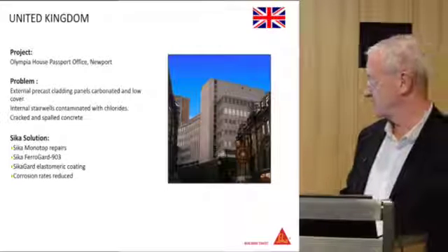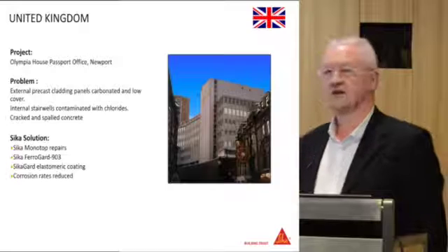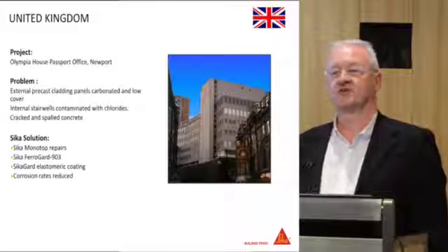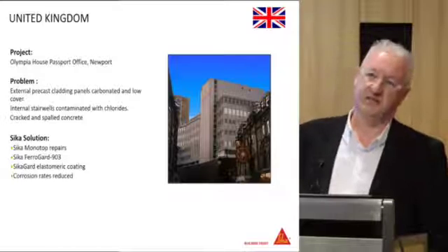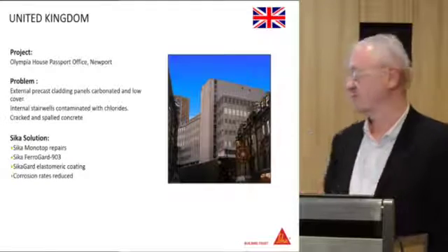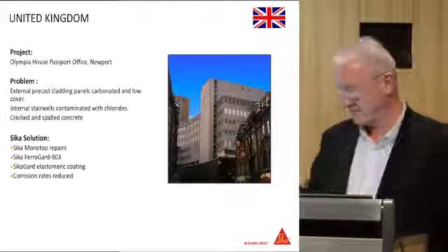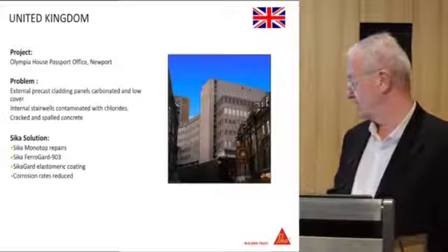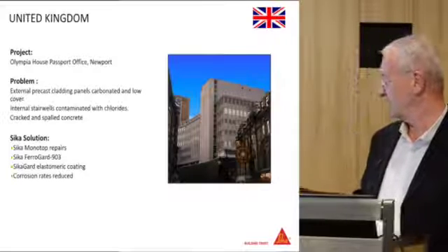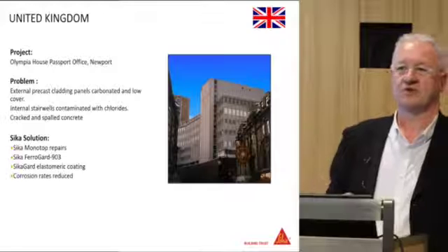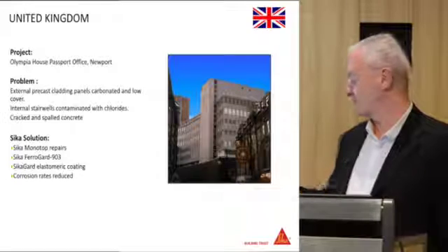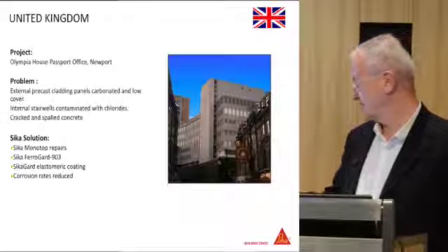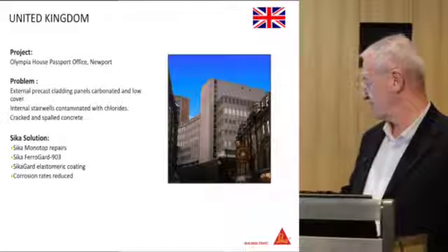After a week, it dramatically took this to 4.5 microns a year. So we're in the relatively safe zone. It just showed you how porous that concrete was for the inhibitor to get through the concrete and onto those bars. Then after 15 months, it had obviously done a lot of work in the first week, and we were down to 3 microns a year, and then after 3.5 years, 1 micron a year. So this has really controlled it from this level down to this level. And of course, as time goes on, it would just continue along here.